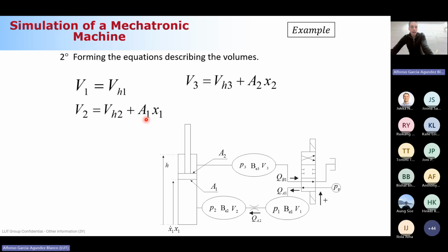And one question, A1 here, how do you compute it? Imagine that in the exam, you need to provide the equations at a higher level of detail. This A1 is just pi times the radius of this piston squared. Perfect, it's a circle. And this A2, remember, is a circular crown, so please don't put this A2 as A1. It is a circular crown. And if you remember in tutorial 6, in Simscape, we had to write this A2 considering the difference of the two circles, as the circular crown. Do you remember? Perfect. So clear the computation of the volumes?